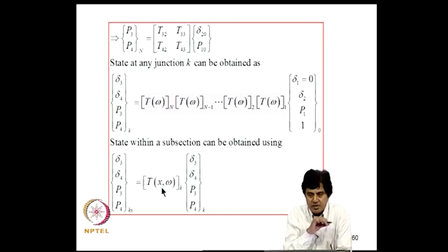Both this dynamic stiffness matrix and transfer matrix methods are special techniques. They have the potential to provide exact solutions, and since the finite element method invariably leads to approximate solutions, it is nice to have an alternate where the solutions are exact. So skeletal structures can be handled in an exact manner in the frequency domain using the dynamic stiffness matrix, and the transfer matrix also can do many things exactly. This is the point that I was trying to make.